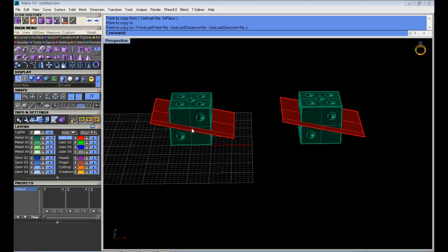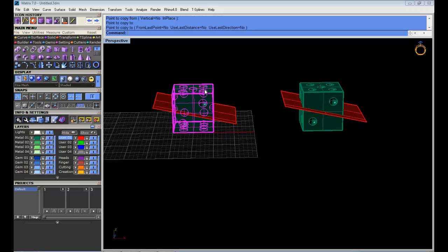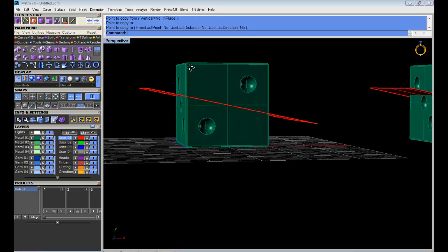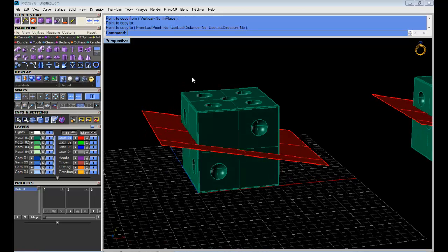Basically what we are doing is splitting the solid by using solids. We could split this object with the surface by using the split command, but then everything inside would not be a solid anymore. The moment we split a solid with a solid, which is actually a Boolean difference, everything is solid again. So it means fewer problems. We will explain that in another tutorial anyway.